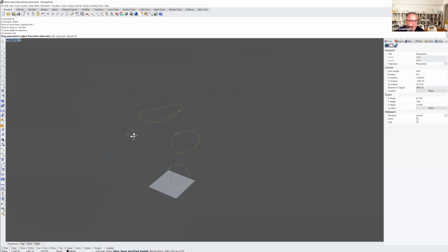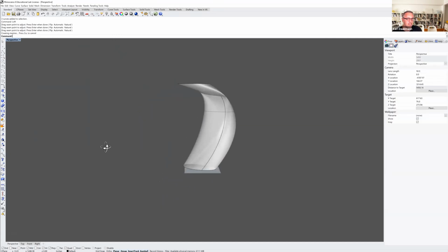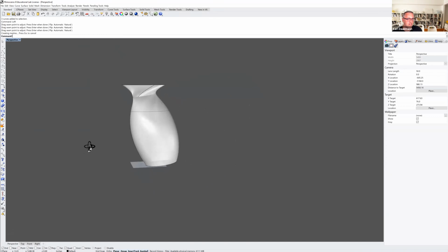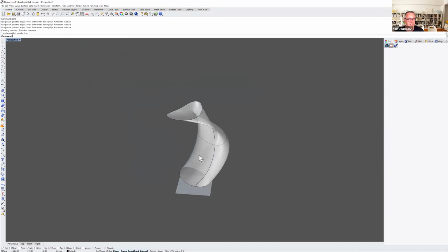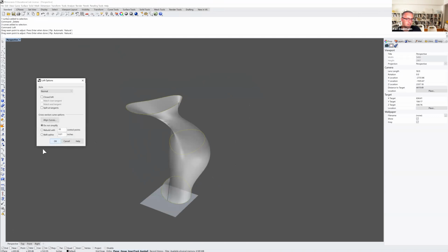I'm not sure, mine, I might have to flip mine. But what you can do is move the point around. It seems like the arrows are all going in the same direction. I'll hit enter. Say okay. So my other one needed to flip, so I'll loft them again. If you click on the arrow, it'll change the direction.